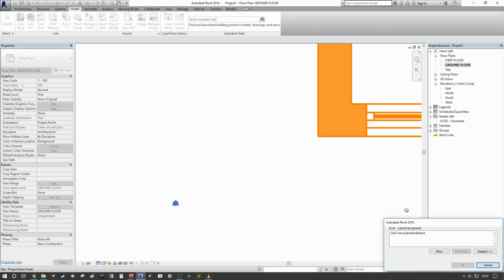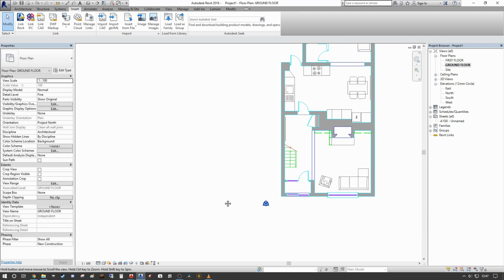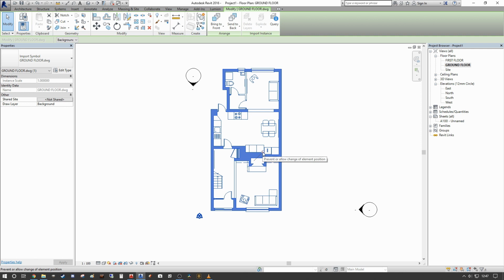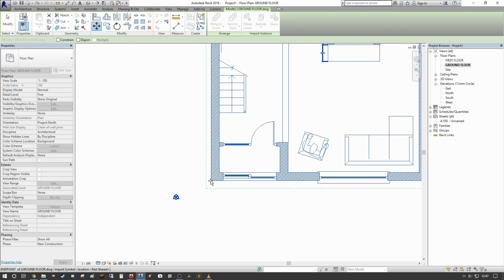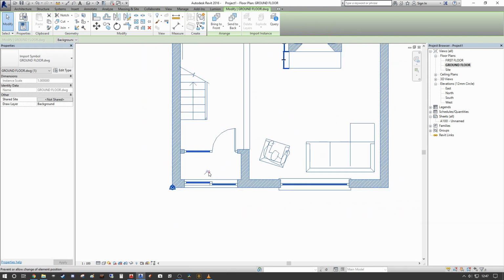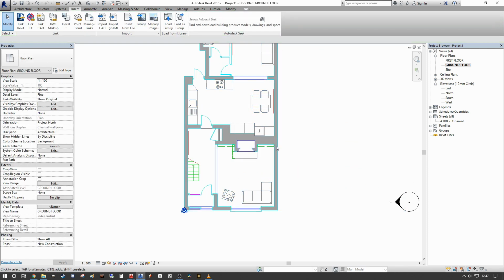quite simply move that. I forgot that I'd actually pinned it, and that's actually a really good note to always try pin your CAD data once you've located it, because it is very common that it can accidentally be clicked and dragged off location. So we're going to unpin it. We're going to move the endpoint to our project base point, and then we're going to repin it. So then I cannot accidentally drag that at all.